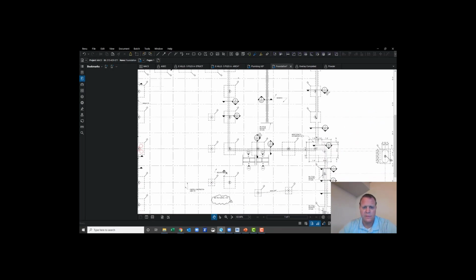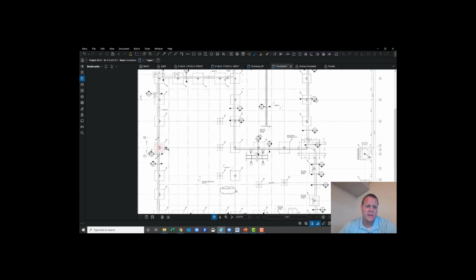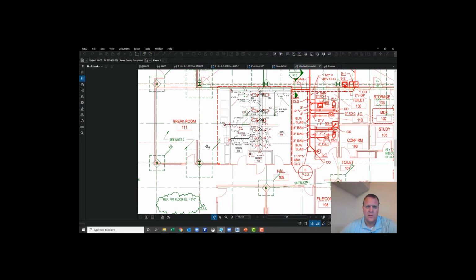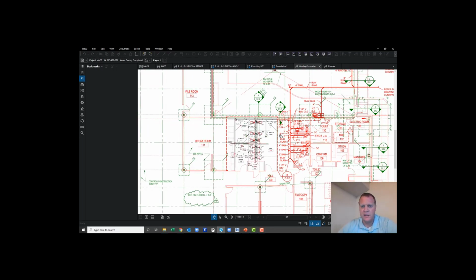And what do we got right there? We got some footings, again, and H columns. And what is under there? Geopiers. So let's go look at that in the overlay as well. And sure enough, all the plumbing is going right over that footing right there. And so it might be worthwhile sending an RFI as well about this area to have the designers coordinate and look at this as well. Most likely they're just going to say move this drain, sorry, the sanitary sewer line, and they're probably going to have it move over here in this space to get it out of this footing.